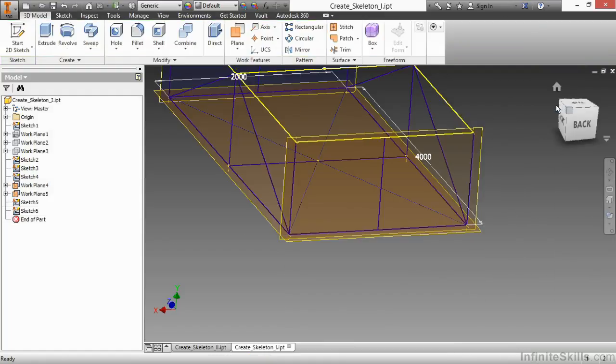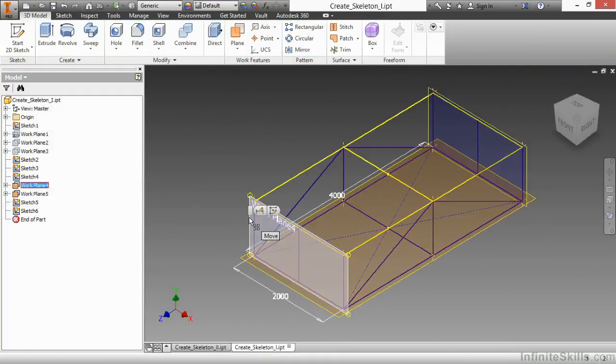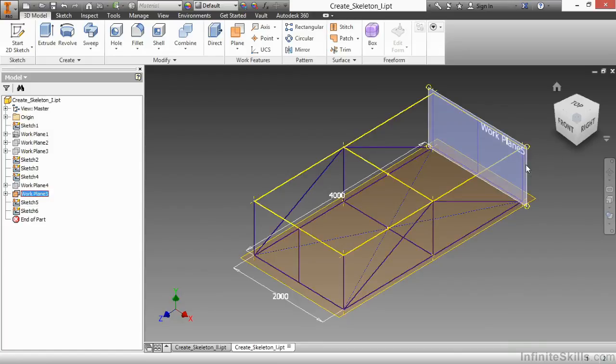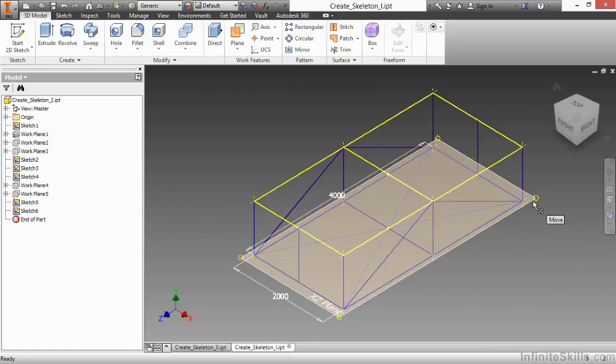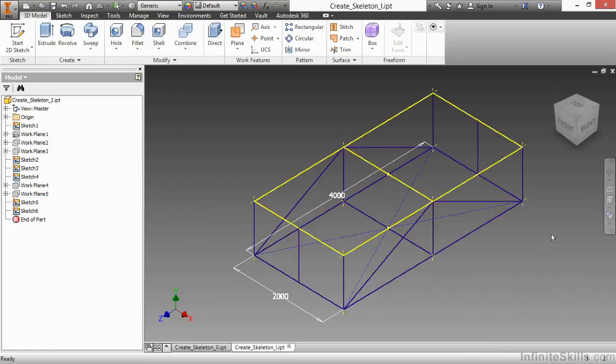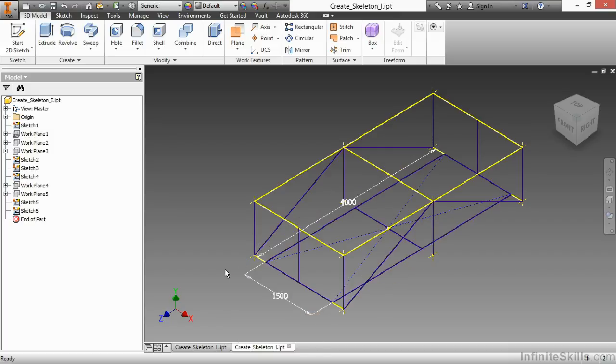Finish the 2D sketch. And I always like turning off the visibilities of these planes because I don't want to see them when I get over into the frame generated assembly and have to place the skeleton. I basically just want to see that skeleton. Now this is all connected with midpoints and geometric constraints to maintain a nice shape for this overall design. If I come to the initial sketch that's currently 2 meters and change it to 1.5 meters and update it, you will see that basic sketch update.